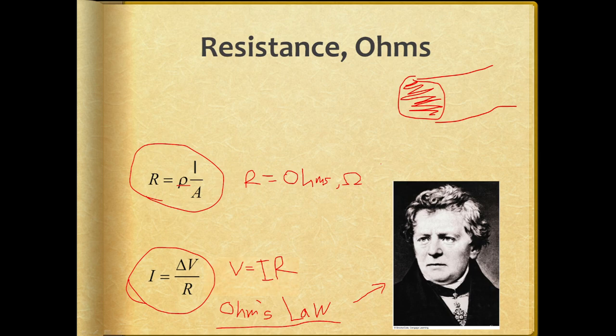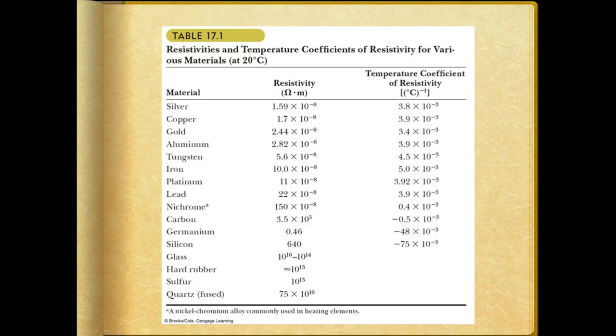We did some similar things for thermal conductivity, I believe. Now, if you were to look at this table, you can look up, say, the entry for copper right here, but there's something to note about the values on this particular chart. There's a second column over here, and the reason for this extra column is that all of these different resistivity coefficients, this first column, are only true at 20 degrees Celsius.